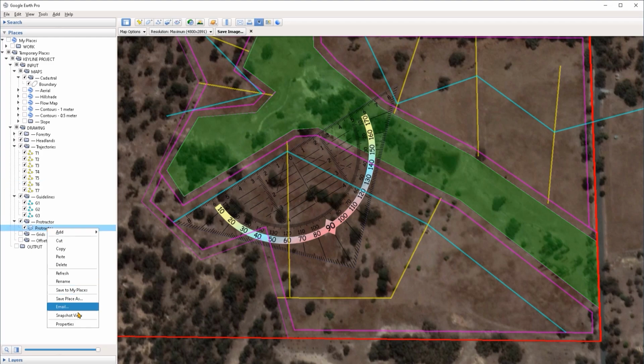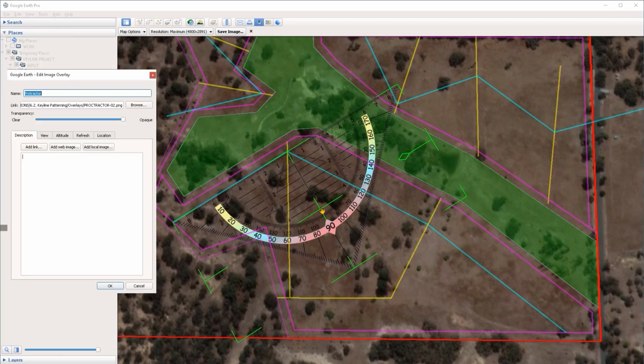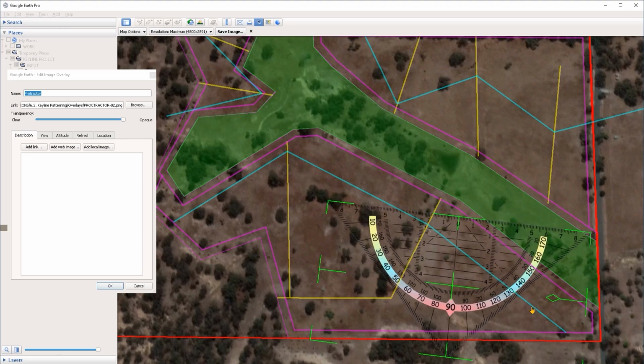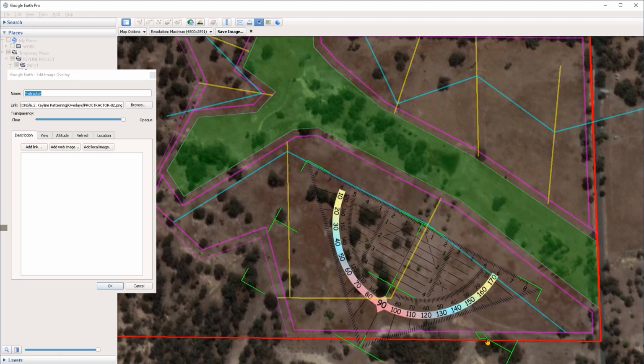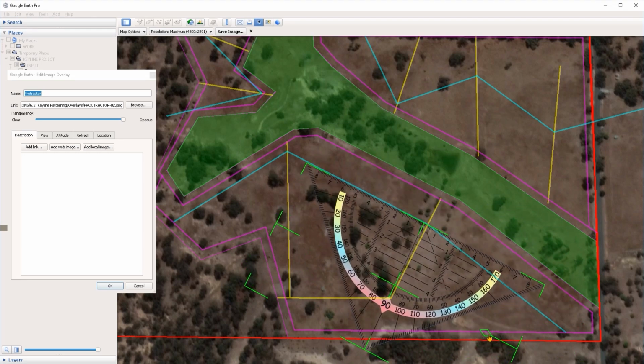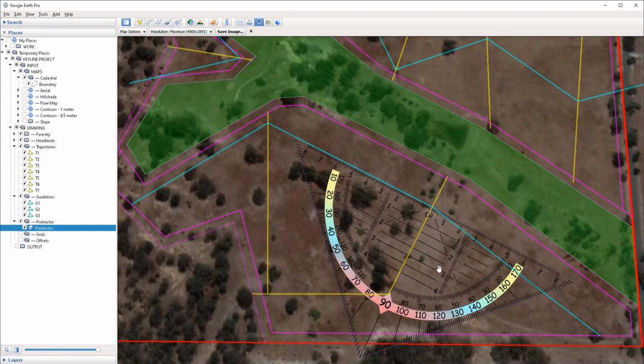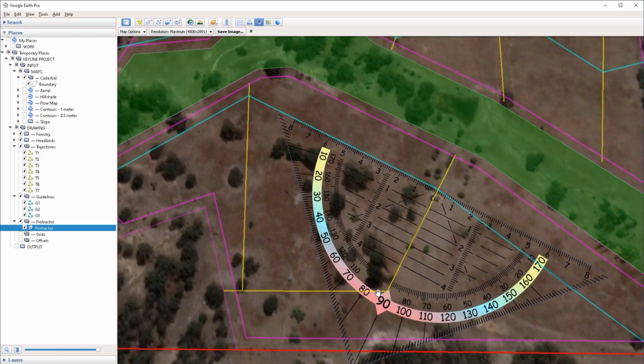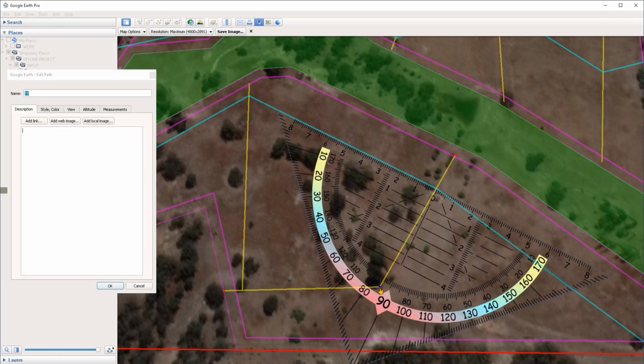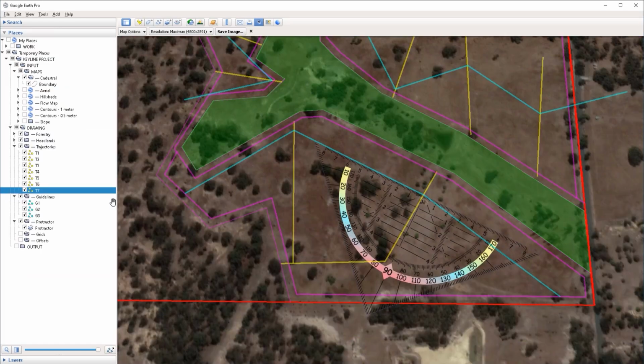So I'm going to right click on the protractor and go under properties so I can move it around to position it into place. Again, I'm going to do the exact same thing, just align the one side of the protractor with the guideline and make sure that the 0 is right at the angle, and I'll press OK on that. And we can see that we have an angle of just about 170 degrees. So the middle point is going to be at 85 degrees. So I can grab the guideline and just move it to 85, and I'll press OK on that. And this is it for the protractor for now. I'm going to hide it.